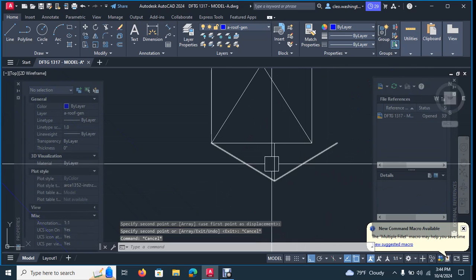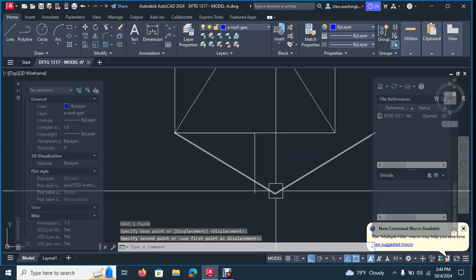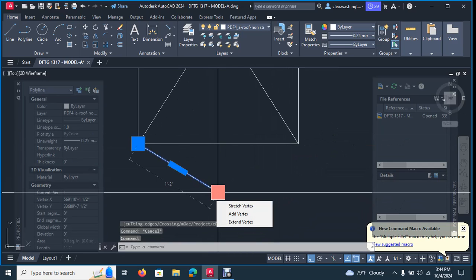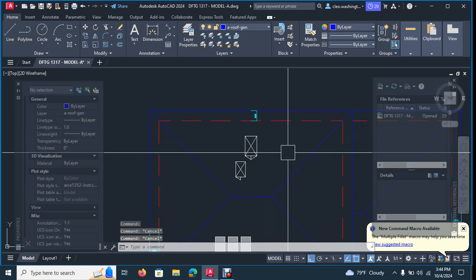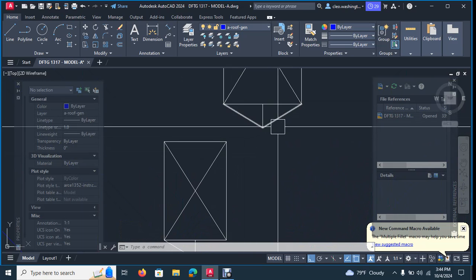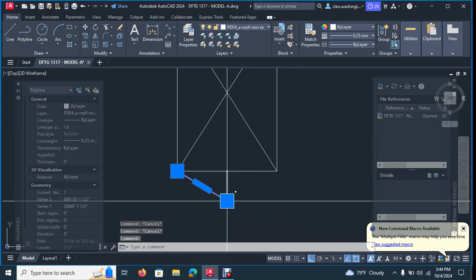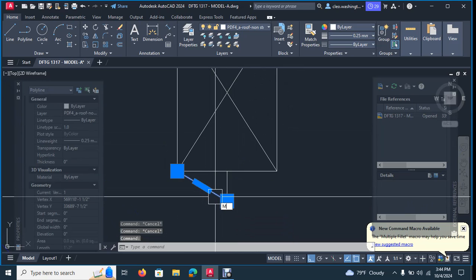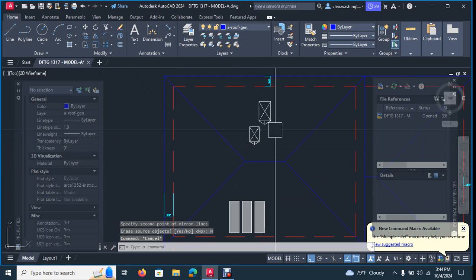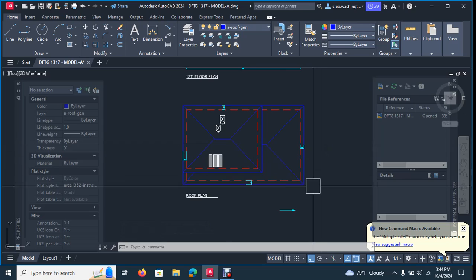And the reason they put these in projects is, keep in mind that the roof is sloping down this way. What happens is this creates a water trap. So you have to put a little small gable here to shear the water off to the left, to the right, and then shear the water off to the left. That's what this is, because you don't want water just sitting there. Water will find and seep its way through a rock if it sits there long enough, right? So that's how you're going to draw your roof plan.